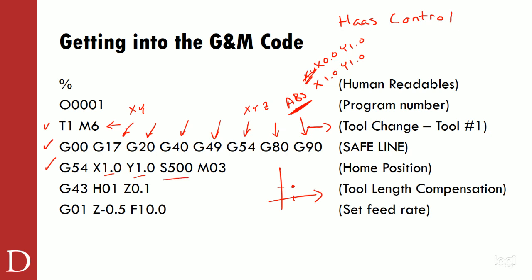We're going to set our speed. It's very important. I didn't tell you what material we're using for this, but in future examples, this is where your speed calculation will go. That's your RPMs. So you need to know what material, how many flutes, the diameter of the cutter, things like that. Then we're going to go into our M03 code. And again, our M03 will be our spindle commands. All right, so turning the spindle on, so on and so forth.